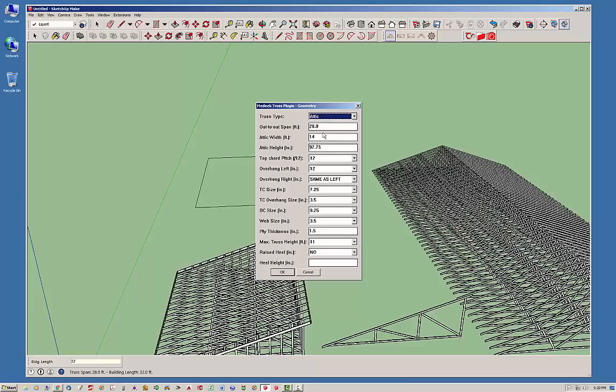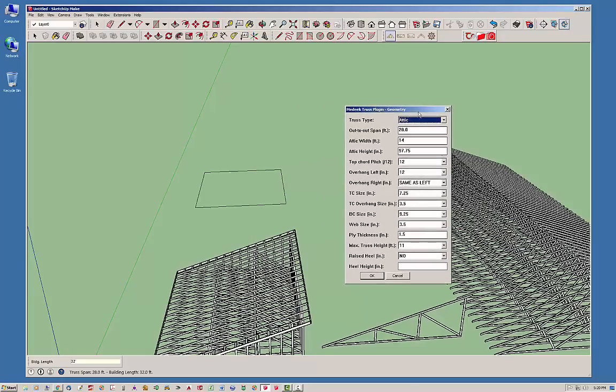But as you can see, this height, you can configure as you like. And I've actually created some logic within the plugin itself, so that if these heights and widths get too far out of what the norm is, then it will auto-correct those for you, or try to anyways. Typically that geometry you've already determined as a designer, or you already have an idea what you want, and then you just put it in, and it'll complain if it doesn't particularly like it. The max truss height, and most of these other options, by the way, are very similar to the options in normal common trusses, so I'm not going to go over those again.